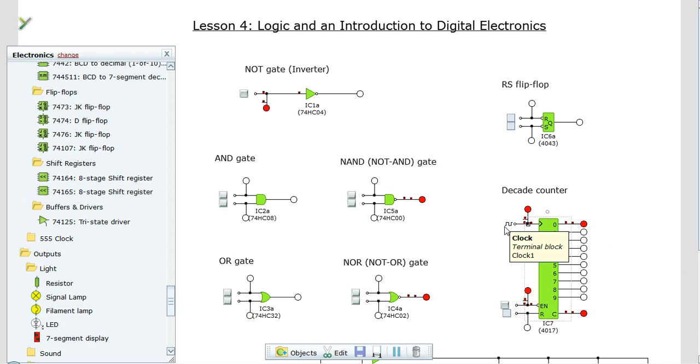So here's how it works. You've got a clock input here, which I've just used. This input is just going on and off automatically. And if I hit the enable switch, all of these outputs go down this row of output loops. Every time this clock goes on, it advances to the next one. If I hit the reset button, it shoots back up to the top, and if I enable, it pauses. So we can pause it and then put it back at the top as we had it originally, or just let it go.